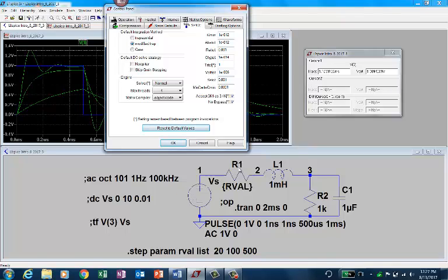Whatever they do in SPICE, if you look at a particular circuit that has R1 between node 1 and node 2, the difference between node voltage 1 and node voltage 2 is R times I. For the inductor the voltage across is L di/dt, and for the capacitor it is the integration of the current. When you have that, SPICE, or any SPICE, generates a matrix and solves it to find all the variables, like voltage and current. Here you are looking at an absolute tolerance of 10 to the power minus 12, and the relative tolerance of all voltage and current.